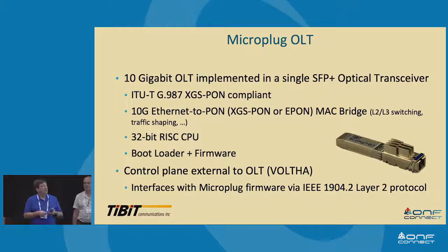It also has to be able to interpret and monitor the bridge for all its capabilities, because it has to apply in the firmware all the SLA capabilities for upstream and downstream traffic, plus all the small tasks in PLOAM to actually handle the PON layer.